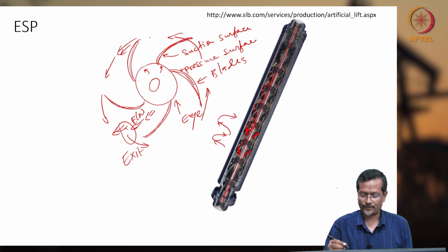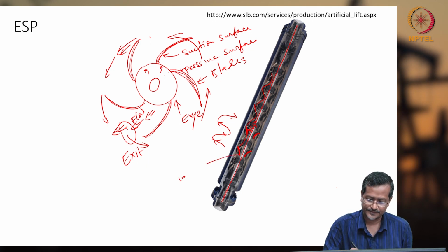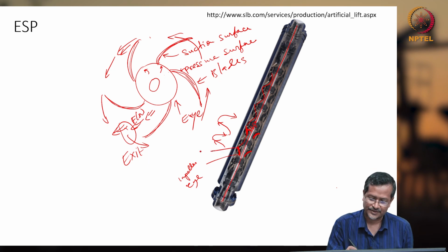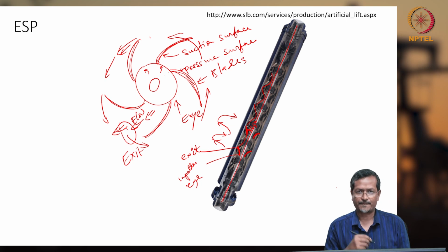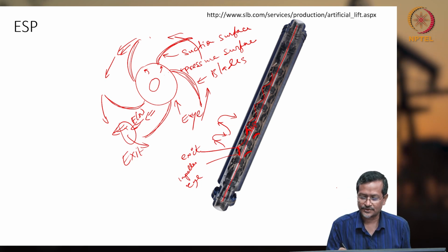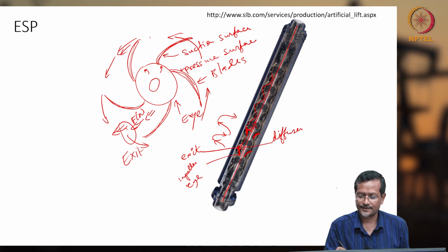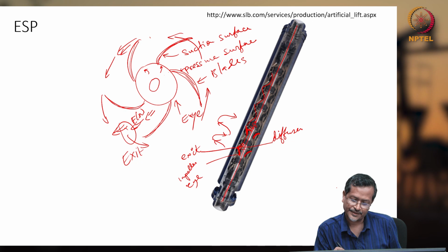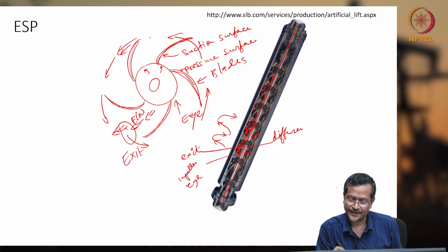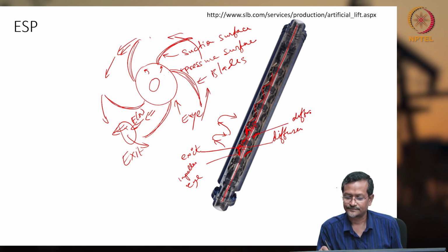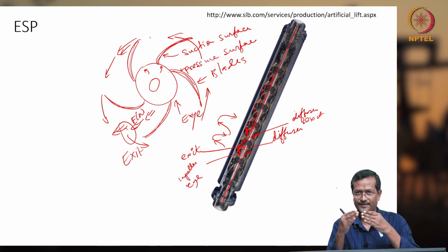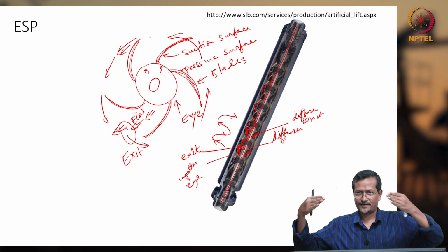Okay, and what is happening? This is impeller inlet. Fluid is entering there, then impeller exit. From the impeller the fluid will be exiting, then it will be entering the next diffuser. So diffuser entry, then diffuser exit, then again impeller. Diffuser exit means this fluid will be nearby the shaft. Again impeller entry, going away, again the diffuser pushing it like this.